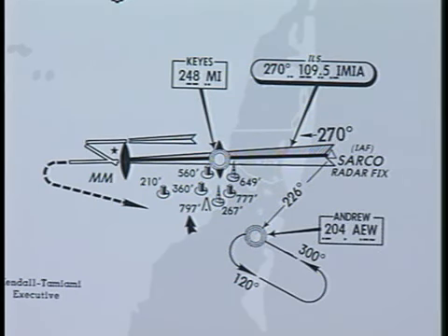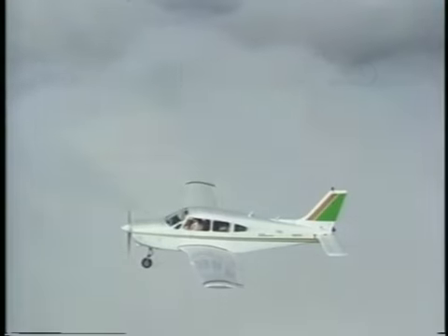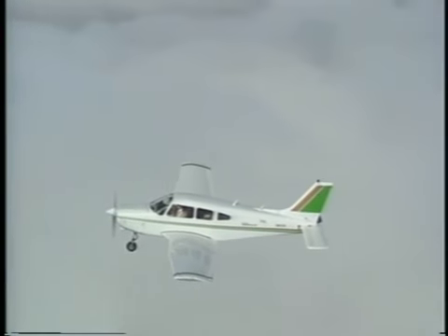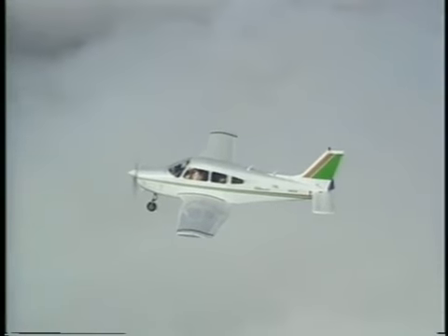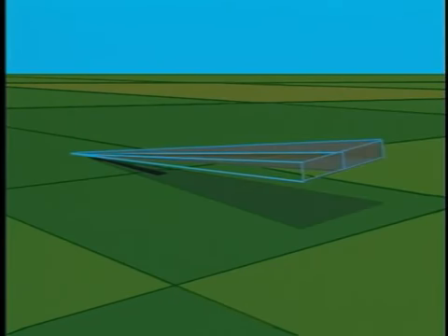The Instrument Landing System, or ILS, is called a precision approach, since it provides both course and vertical guidance information. Because it's so accurate, you can usually descend to a lower minimum altitude than with other approach procedures. Lateral guidance is provided by the localizer, which radiates a navigational signal along the runway centerline. When the signal is projected in this manner, it is called a front course localizer.